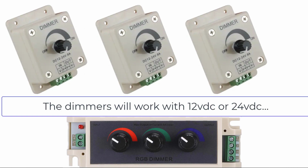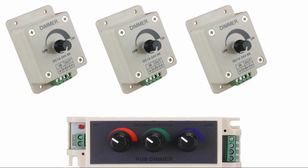So this bottom dimmer with 3 knobs on it, you put the 12 volts in polarity-wise. That red LED will light up to show you got power. And then on the other end, the plus V goes to the common on the LED strip, which is going to be either black or white. And then you've got RGB wires that go to the red, the green, and the blue on those LED strips.